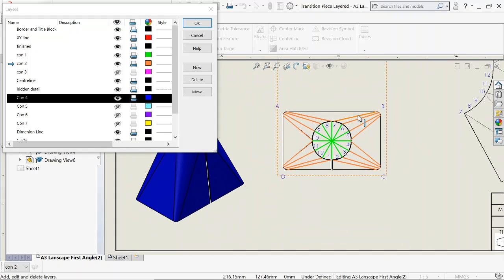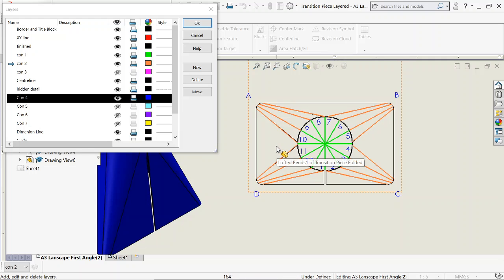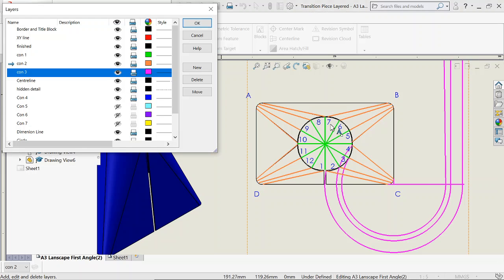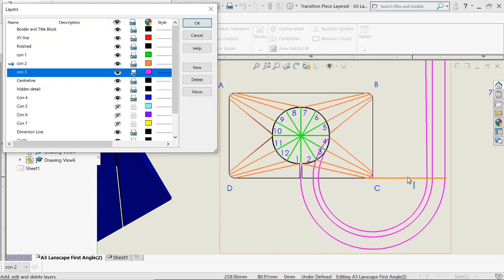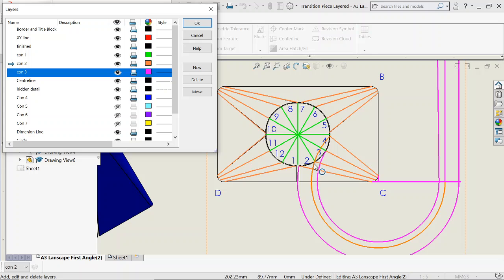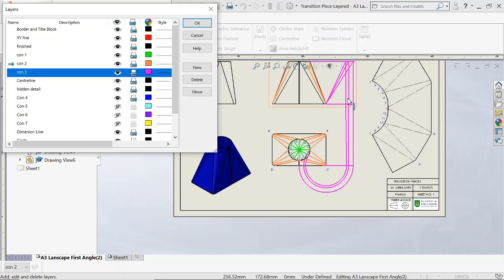When we're this far, the next step is rebatment. I mentioned rebatment in the previous pages in the portfolio, and this is where we're going to find our true lengths for the lines in elevation. For this, we extend out our line. This is the corner piece that I was on about. So we extend out our line, then from 4, 3, 2, and 1, so we can see the same arc contains 4 and 2 and 1. So we're setting up our compass. Point C is our point of rotation. So we're rotating around until we hit the horizontal line here with the 3, with our compass or the circle tool on this.